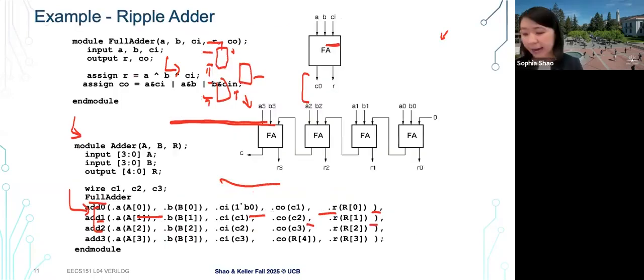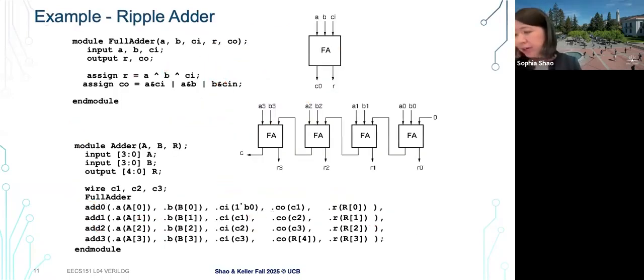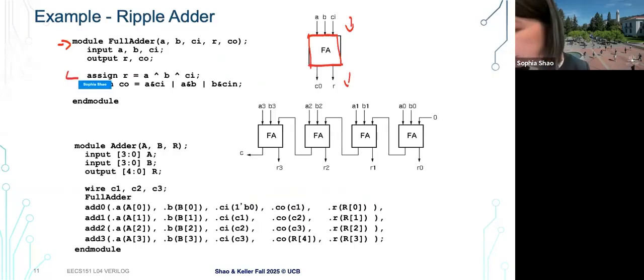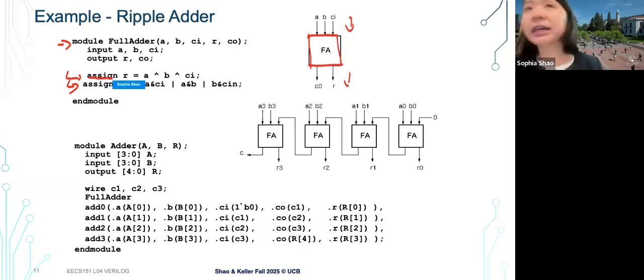And you'll see similar patterns here. This is another example, the adder example. We'll spend more time on adders later in the semester. But you can see we have a module, a full adder, with inputs and outputs, and everything here is combinational. For my adder module, instead of instantiating basic blocks like AND and NOT gates directly, as we mentioned earlier, we can use the assign statement.